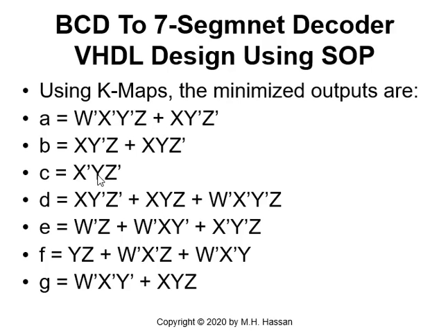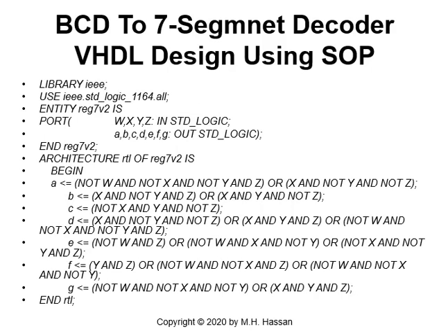Once I have those functions, I can generate the VHDL code by implementing those functions as logic equations using a sum of products representation, and this is coming in the next slide. So this is a higher level of abstraction than the truth table, but it is lower than the gate level abstraction. It's called the RTL level of abstraction.